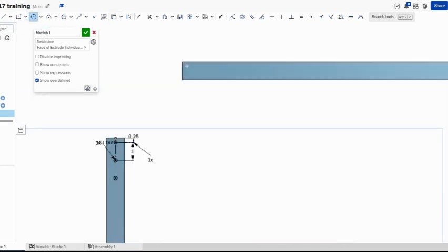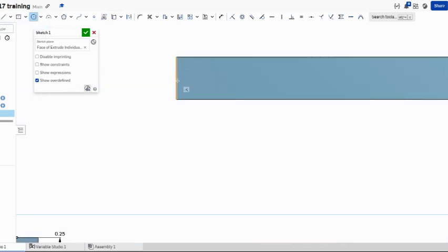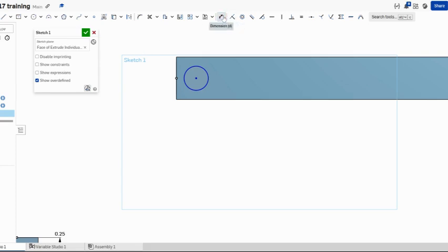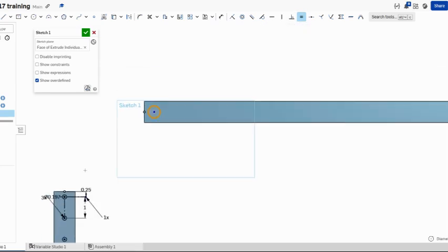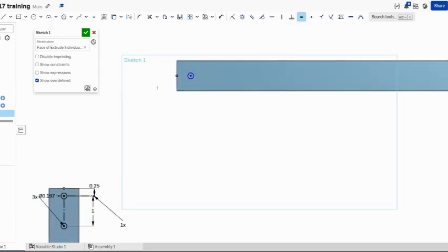So again, the circle tool, zoom in. When you find the middle point, you just bring your mouse, those orange dots, you can see the constraints. So this is horizontal to the midpoint of that. Now, when I do multiple circles, instead of setting the diameter, I'm going to use the equal sign so that I can automatically change it.